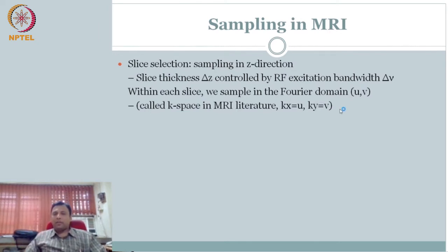This is again the bigger problem in this domain. Each time we think about sampling, we introduce the concept x of t or y of t, the signal in the time domain, and we say, oh, sample it at twice the highest frequency to beat the Nyquist, and that's how we do the sampling concept. Here it is kind of weird. The signal that you're recording, as we saw, is actually the frequency spectra. So what you're recording is a sampled version of your frequency spectra. That's where the confusion may start to arise.